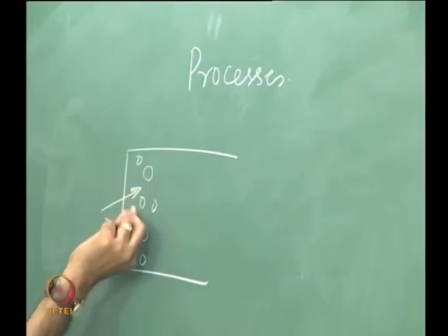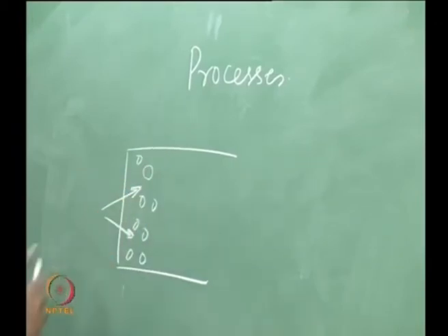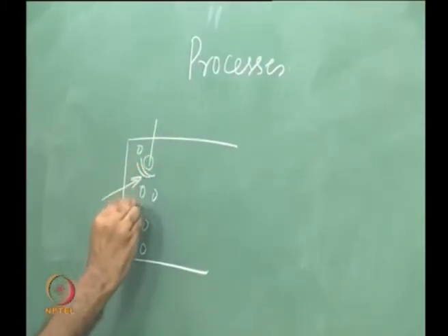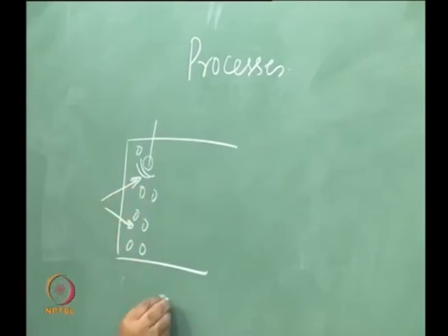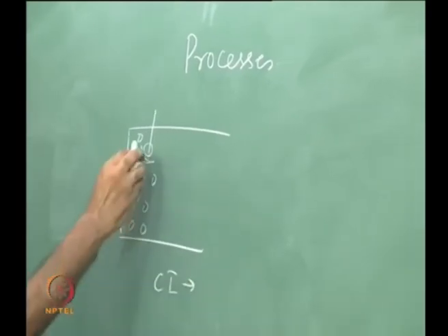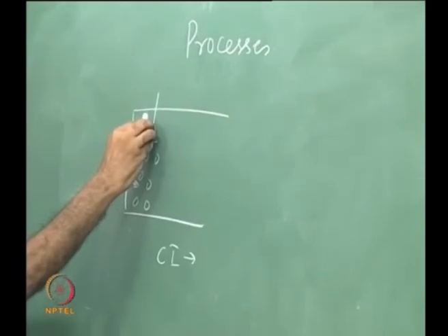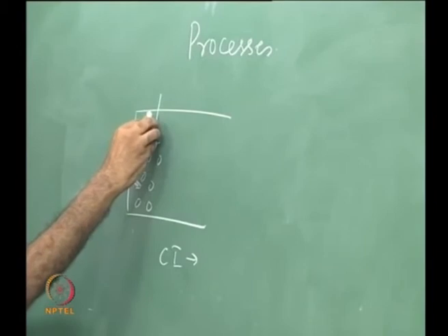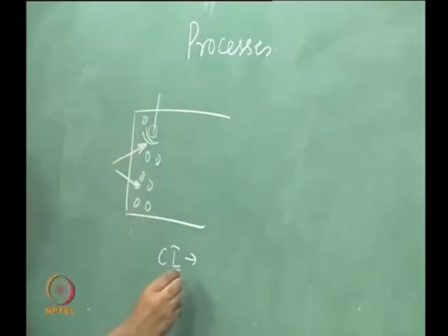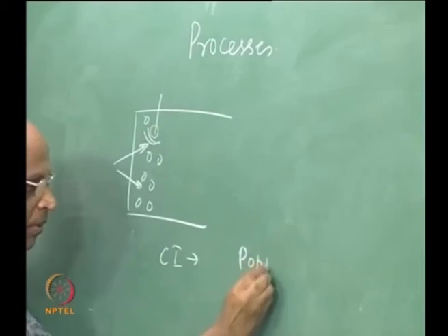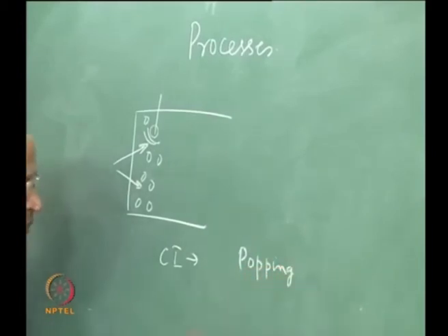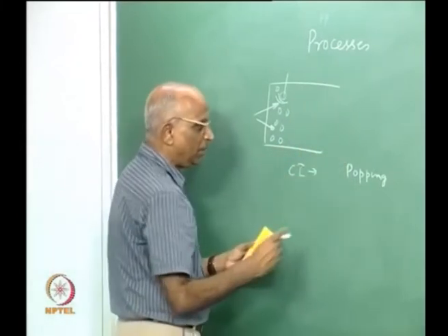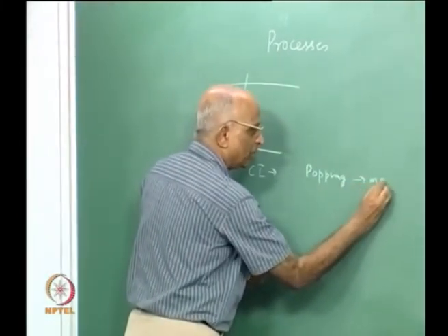In the stoichiometric region, the fuel burns readily and creates wave motion, and this wave motion could lead to combustion instability. Very often the stoichiometric composition, when heated, is so powerful that it creates explosions which create wave motion, and this is known as popping. You hear a popping type of sound, it couples with the chamber acoustics, and therefore you have popping instability, which is essentially due to mixture ratio variations.